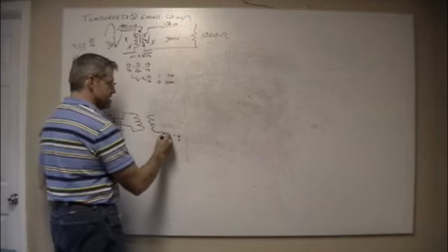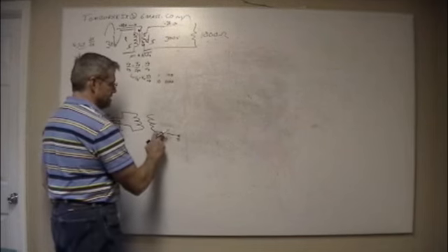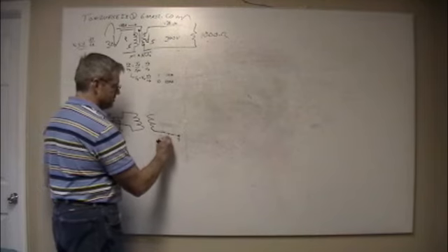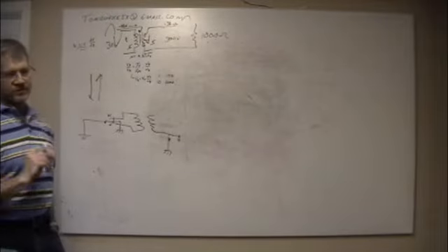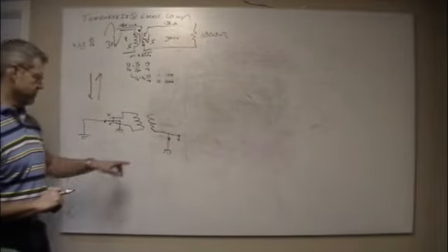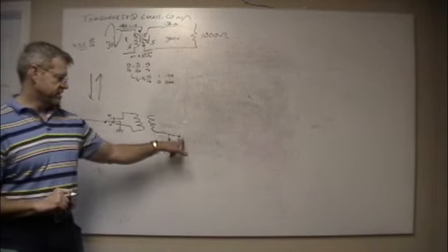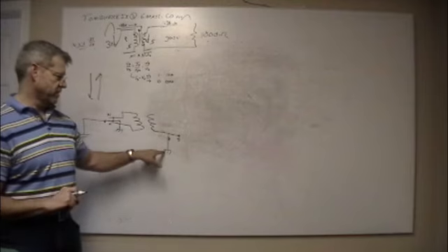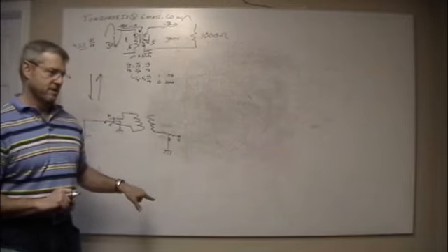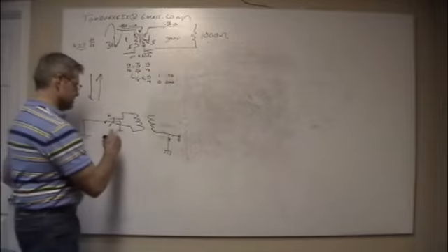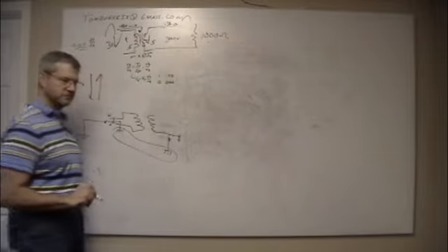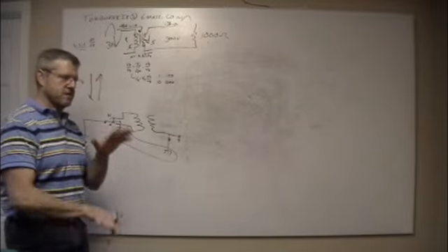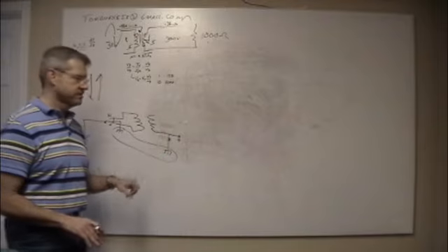And it could well be, in some cases, that he's not tied up. Chassis is tied up and there's some resistance here. On purpose. Okay. So these 2 grounds are the same, but these 2 are not necessarily the same. If there's any current flowing, then they will very suddenly not be the same. But this will still get anchored to ground because this is the same symbol. And this will blow up or do whatever it's going to do. But there are times when you do it this way and there's reasons to do it.